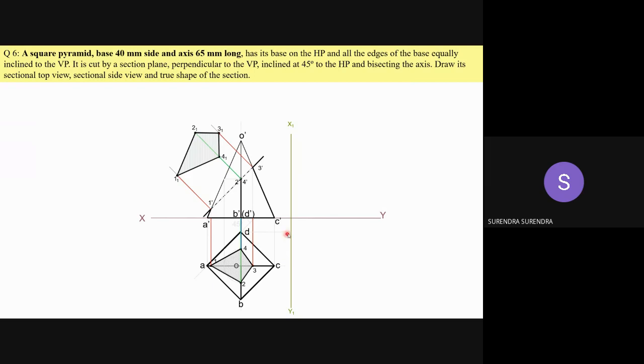With the intersection point of XY and X1 Y1 as center and taking this as the distance, draw an arc. You should draw the complete arc from X1 Y1 to XY. Some members drew part of it and completed the remaining with a straight line. Don't repeat it.